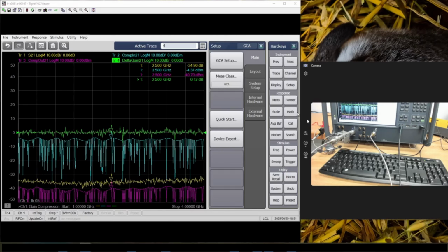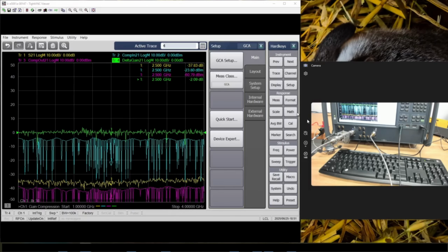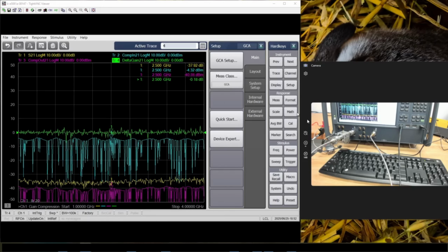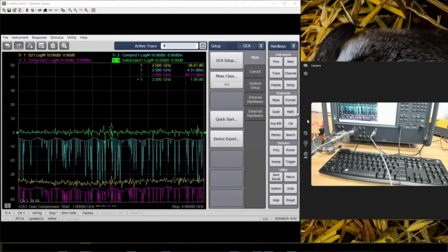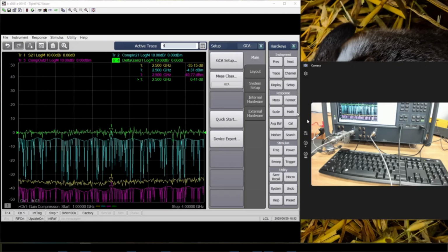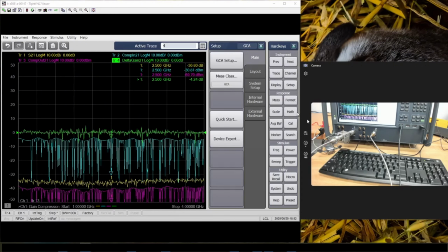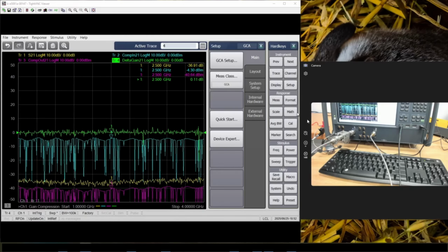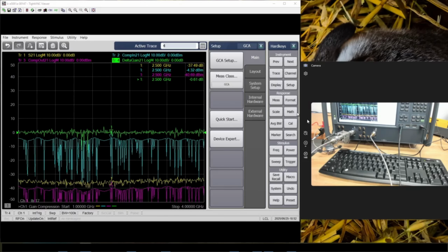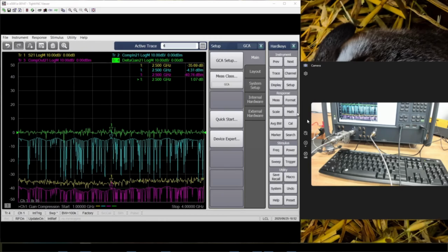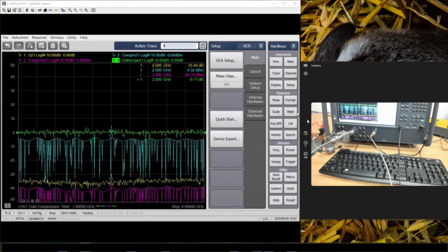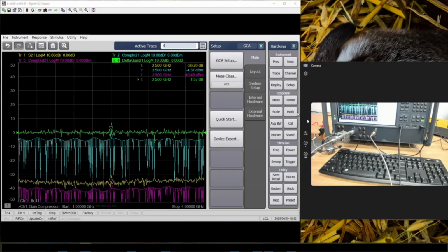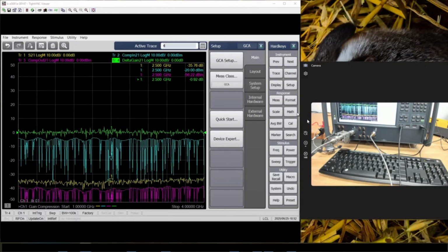So the definition for gain compression measurements is that when there's a change of 1 dB in the input to the amplifier, there is less than a 1 dB change on the output of the amplifier. So in linear zone, it works out like the formula y equals mx plus c. So anything changed on the x will change the value on the y. So for example, if I change 1 dB on the x, in linear zone, the y will change by 1 dB.